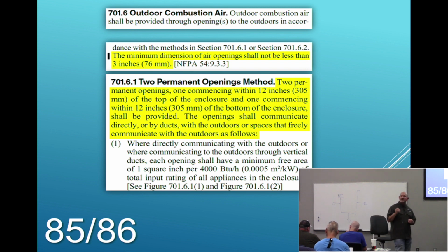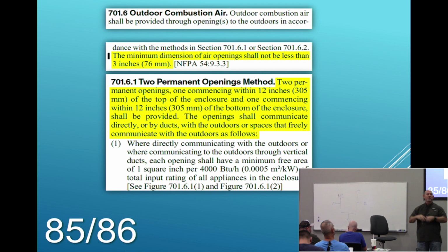Now listen guys, the reason I'm being so picky with you is those 2 rules are the same. Minimum dimension at least 3 inches. I need a hole within 12 of the top and a hole within 12 of the bottom. And then nothing else agrees. But the problem is because those first 2 rules are the same, people say, oh, they're all the same. They're absolutely not the same. These are the only 2 rules that are the same: 3 inches in dimension and 12 of the top, 12 of the bottom.